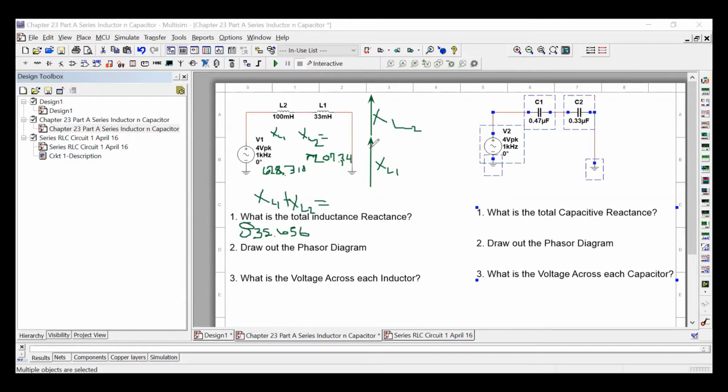They're not pointing in opposite directions, in other words, down 180 degrees. If they were, we'd have to subtract them. They're both facing up. It's great. We don't have any resistive components, any passive components on here. We just have some active components. So there's no need for trigonometry on this. So the phasor diagram is up there.